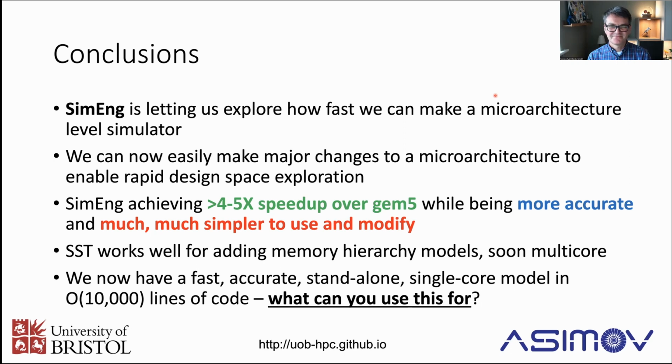Interesting. Very interesting. How do you model, for example, the memory traffic? Because we have seen, when you compare different architectures, for example within the caches, some data traffic can overlap, some cannot overlap, and stuff like that. So how do you model this? Yeah, great question. In some ways, the way the memory hierarchy works and the way the microarchitecture, the core model, interacts with memory is probably the most important thing for accurately understanding what's going on.